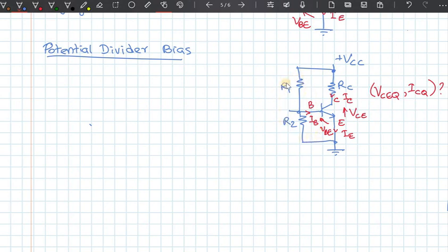Say for example, the current should be 10 or 100 milliamperes, which requires R1 plus R2 to be in the range of 100 ohms or maybe 1k, so that if VCC is 10 volts, divided by 1k would be 10 milliamperes. So at least that, so this should be less than that.